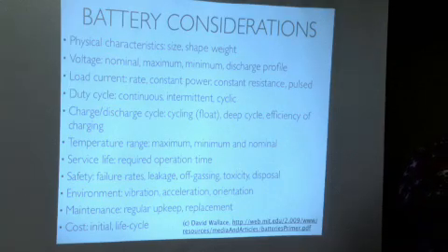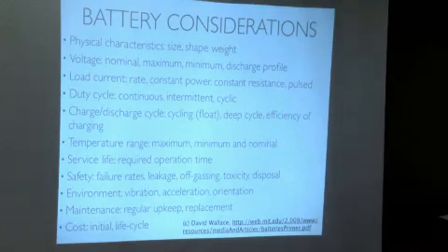So for example, a car battery as opposed to a deep cycle lead acid battery, both are lead acid. One of the differences is that with a car battery, you need a high current for a very short burst of time just to get the starter motor to run, and then your car is set, and you can recharge it thanks to your alternator when you're driving your car. So the car battery almost never discharges unless you leave your lights on all night. Bummer. And then your battery's dead, and you probably need a new one if you do that a few times.